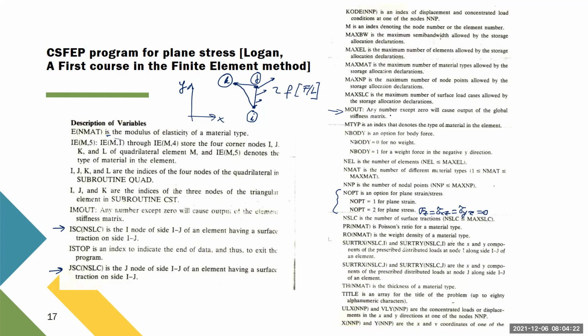But if it is a very long example, then this is an extremely large stiffness matrix with a lot of numbers, and it's going to be quite complex to make any sense out of them. If you develop this with just one or two elements, it's a good idea to check what's inside this global matrix. If not, I just put 0, so I have no matrix printed in my result file.